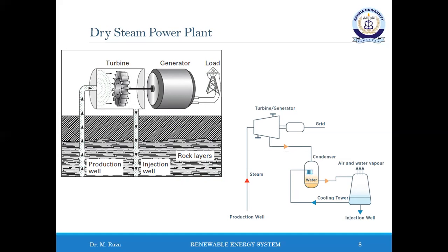Passing through the turbine, the steam expands, causing the blades and shaft to rotate and hence generate power. In the simplest form of power plant, a back pressure unit, the low pressure exhaust steam is vented directly to the atmosphere. Although such units are simple, they are also very inefficient. The system efficiency is improved by adding a condensing unit.